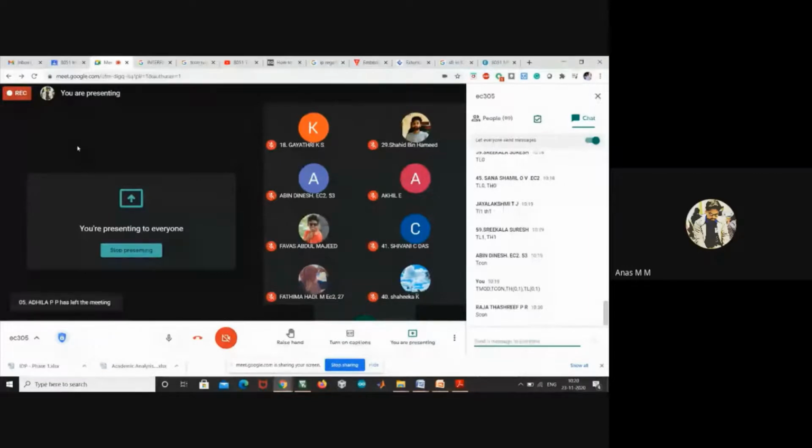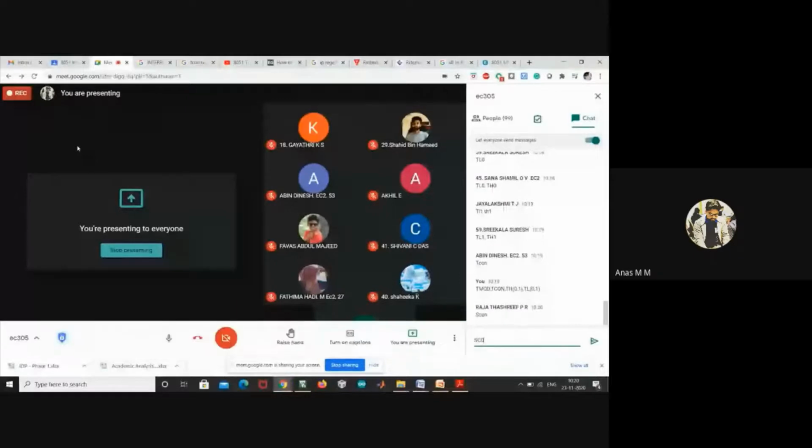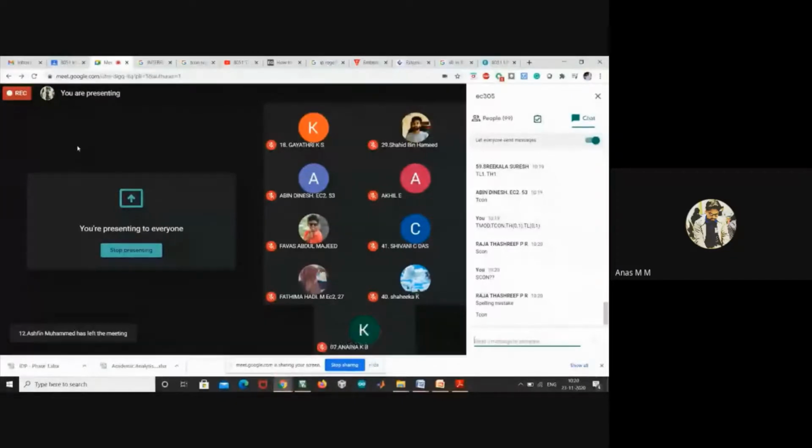Basically, TMOD, TCON, TH and TL are what we used for timer programming. Did we use SCON for timer programming so far? It is not a spelling mistake, it is TCON. The SCON register exists too. Anyhow, these are the registers we used in the previous classes for timer programming.